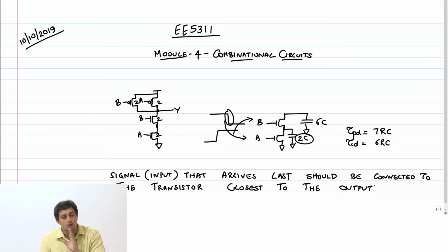right? So this statement is true even if I have a NOR gate. If I have a NOR gate with a PMOS stack, then the input that arrives last should be connected to the PMOS transistor which is closest to the output. Clear?